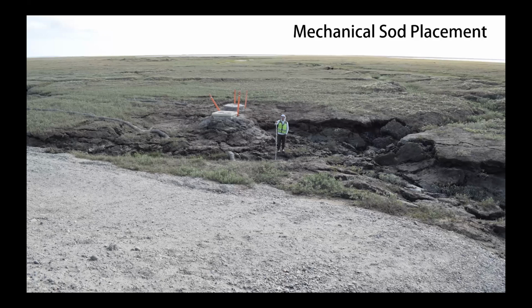We backfill this in places that are water filled, we fill and squirt the water out by the fill. It's not a great technique because the fill gets really wet and soft and it's hard for the heavy equipment to manage, but dewatering is beyond us. What we need is a truck. You have to dewater into a truck and then you have to find a disposal site. And that adds a layer of logistics and cost that's kind of beyond us.